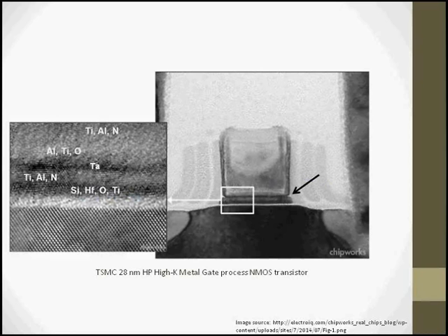Also, for a contact type process, touching down to our sources and drains, is typically an oxide etch that has a nitride etch stop where it meets the source and drain. This might be another good application for ALE, where we're trying to clear the nitride in a very controlled, gentle manner without damaging the source and drain substrate below, which will help improve the contact resistance.